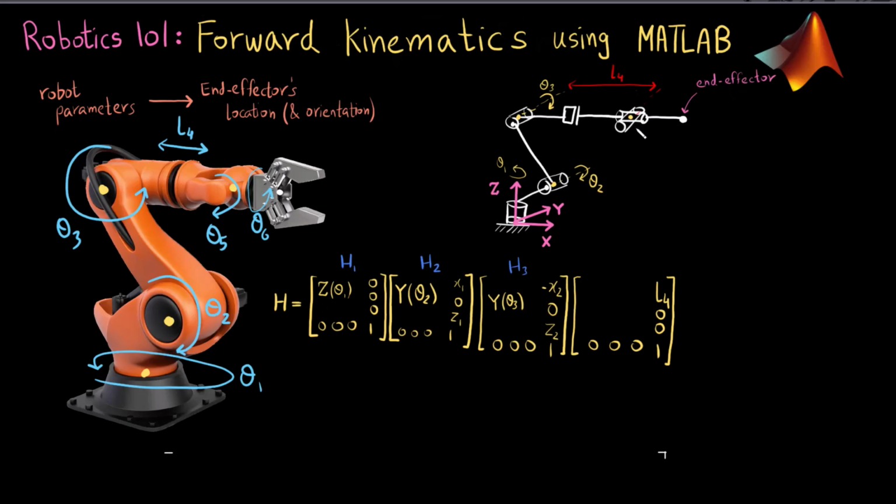And once I get to this point, now I can see that first there is a rotation about the y-axis, which is theta 5. I am talking about this one. So first there is a rotation about the y-axis, theta 5, and then there is a rotation about the x-axis, which is theta 6. So I can combine those two: first a rotation about y, which is theta 5, and then a rotation about x, which is theta 6.